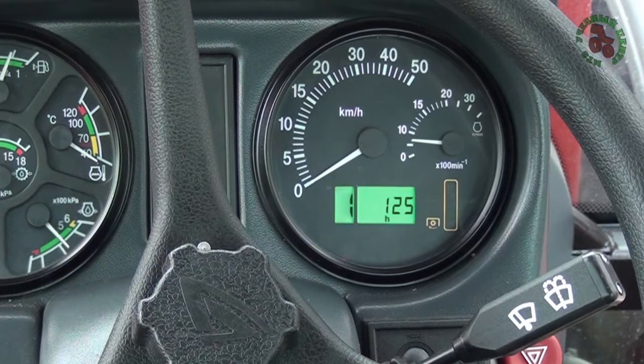Lightning segments and indicators of PTO speed display the rear PTO speed. At turning on rear PTO, the following takes place. The indicator 540 revolutions per minute lights up, and when speed 320 revolutions per minute is achieved, the lower segment lights up. With increasing speed, the upper segments light up simultaneously. When the speed 740 revolutions per minute is achieved, the indicator 540 and all the segments switch off.